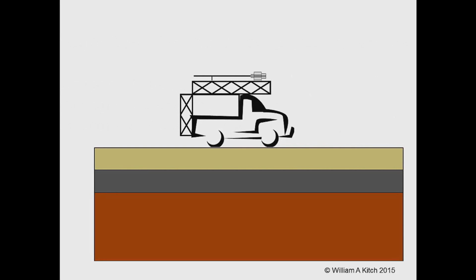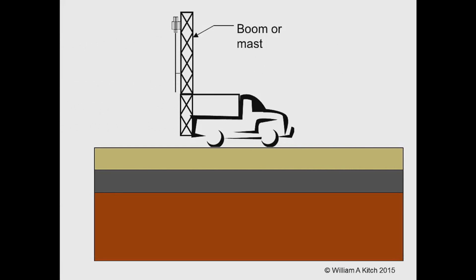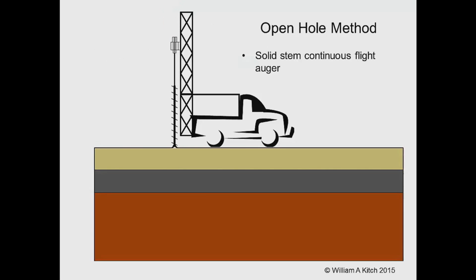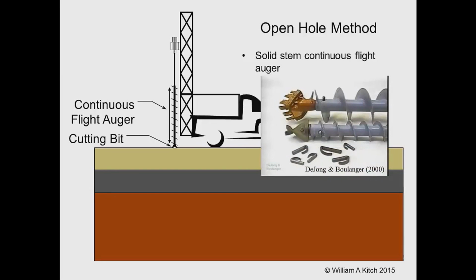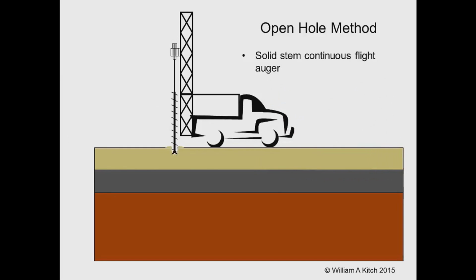Number 3. Category C sampling methods. By using Category C sampling methods, the structure of the rock mass and its discontinuities have been totally changed. The rock material may have been crushed. Some changes in constituents or in the chemical composition of the rock materials can occur. The rock type and its matrix, texture, and fabric can be identified. Examples: sampling of cuttings by rotary open hole drilling.